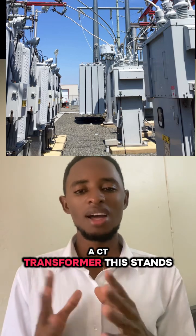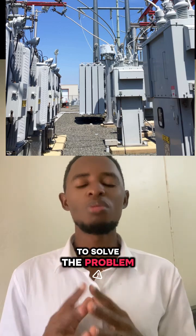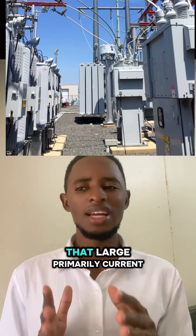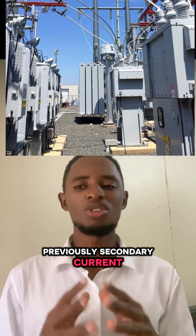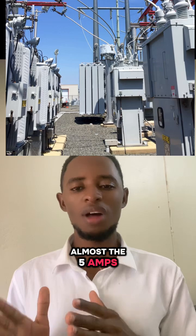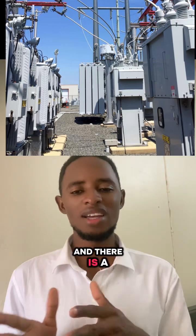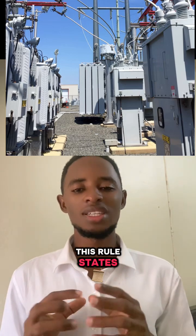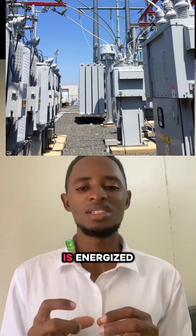A CT transformer stands for current transformer. A current transformer helps us solve the problem of measuring large line current safely. A CT steps that large primary current down to a smaller, precise secondary current, typically 5 amps to 1 amp, that instruments can handle directly. And there is a rule that governs the current transformer. This rule states: never open a circuit at a CT secondary while the primary is energized.